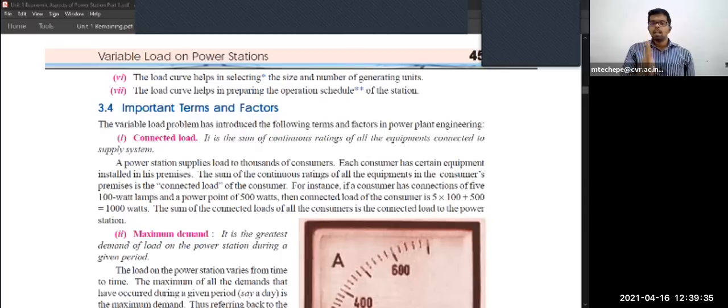Say, for example, 12 p.m. to 1 p.m., what is the load? 13,000 megawatt. In that particular station, say 1,500 megawatt is the maximum installed capacity, so 1,000 megawatt you can maximally generate. Like that, many generators will be there, 100 generators or 50 generators.